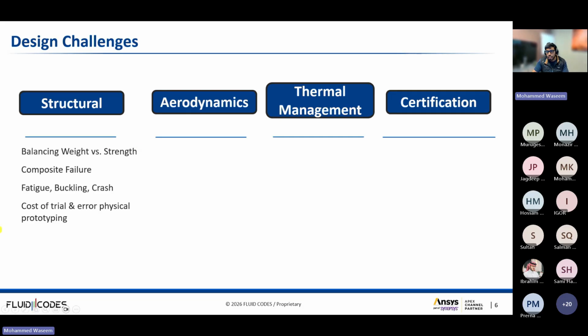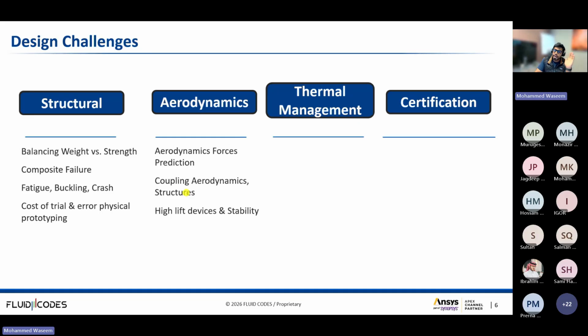If we wait until physical testing to find these issues, the cost and time for redesign really become expensive. Another main challenge with aerodynamics is the accurate prediction of aerodynamic forces across different flight conditions, such as takeoff, climb, cruise, and maneuvering. These aerodynamic loads affect the structure, and this is why we couple CFD to structures to understand how your structure behaves under those aerodynamic loads. Here we evaluate aeroelastic effects such as fluttering. In aerodynamics, we also care about high lift devices as well as stability.